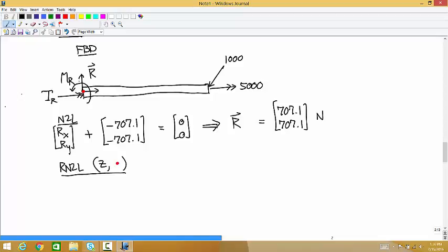It's producing a moment about the z-axis, so we just add that one on. What about torque T_R? That's in the x direction, about the x-axis, so that doesn't produce a moment for this equation. What about R? It doesn't, because it's acting at the about point.